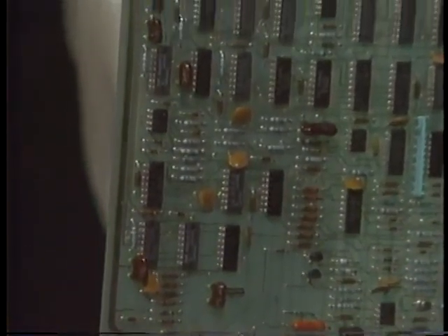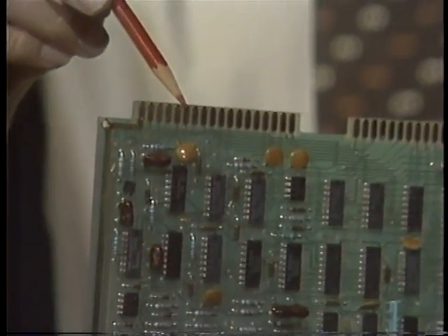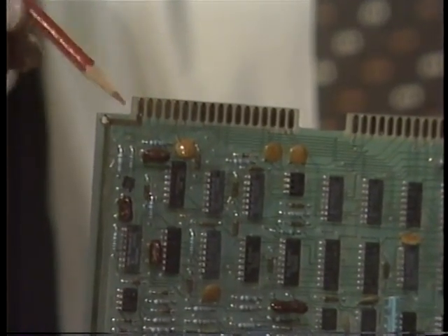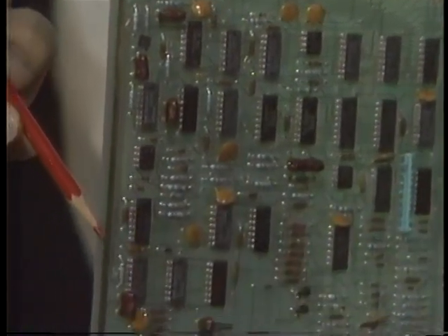If a static discharge takes place to one of these pins, it can zap more than one component. Our protection statistics bear this out. Over 70% of the parts which fail after they are loaded onto assemblies are those which are connected to input and output pins. These become freeways for electrostatic zap.